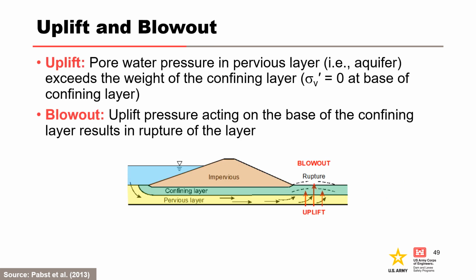If the uplift pressure exceeds the weight of the confining layer, uplift can initiate and result in significant changes in the seepage regime. Uplift can form a new seepage exit beneath the confining layer, where hidden deterioration can occur from concentrated seepage if horizontal gradients are high enough.